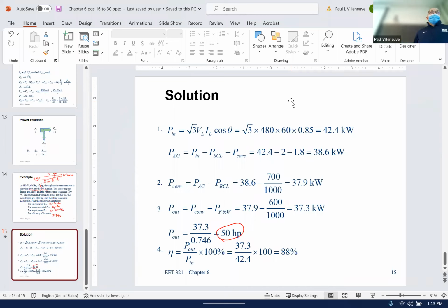You remember how we take a motor and put electrical power in to get it to spin, a magnetic field, and they chase each other? If you alternate the direction, you can make that motor act as a generator. So when you apply your foot on the brake just slightly, your brake pads don't squeeze. It actually causes a magnetic field to rotate backward, and you take mechanical energy out, and because now you have magnetic fields chasing each other in the opposite direction, it slows the vehicle down. So regenerative braking is your motors that are driving your wheels operating as generators. They're recharging the battery.